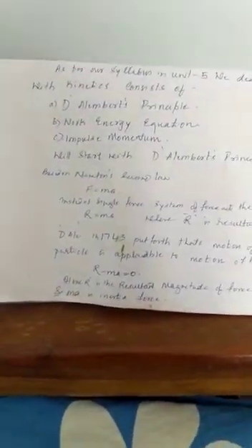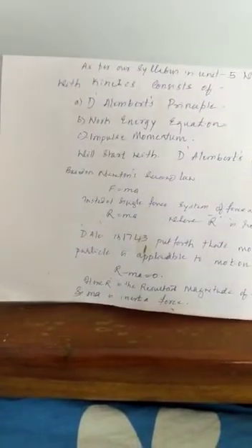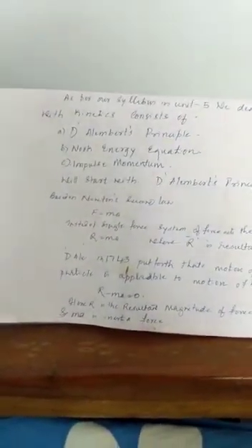We can slightly modify this equation to R minus ma equals 0. I brought the mass into acceleration to the left side, so the equation becomes R minus ma. Here R is the resultant of the force system, that is the net effect of any system of forces acting on the body, and m into a, mass into acceleration, is called the inertia force. When the entire body is moving under the action of a resultant force, it is under dynamic equilibrium.